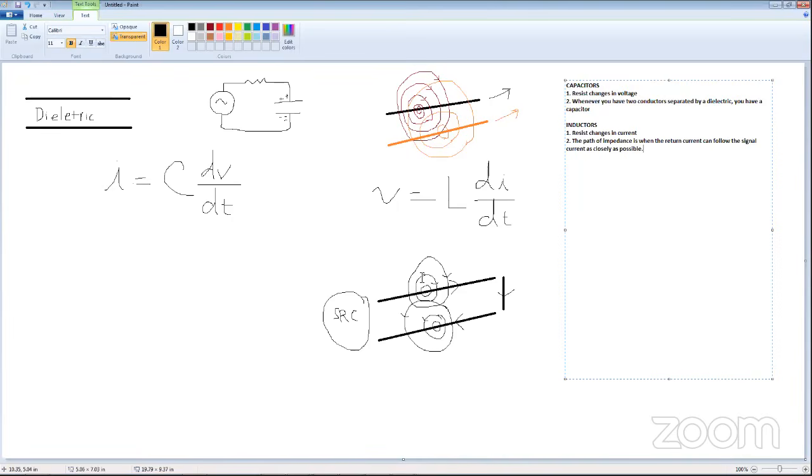So again, most of the time you run into these things when you're dealing with high frequency, as both examples that I used show. So if you're in the hundreds of megahertz, heading up there, you need to start worrying about this stuff. So, Wi-Fi, anything related to Wi-Fi. Yeah, Wi-Fi, IoT. Now, the caveat to that is most people that do those types of products just buy the modules. So if you have an ESP32 module or something like that, it comes all in this one module. All this craziness has already been handled by the module. It's already calculated for you, so you don't have to deal with it.